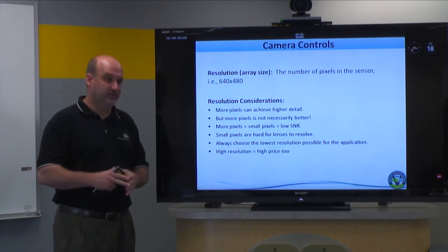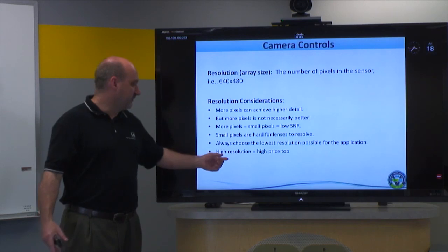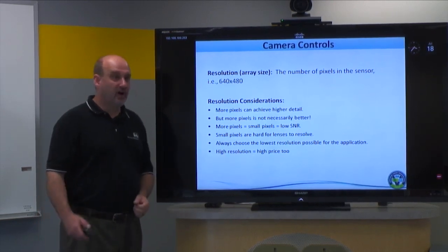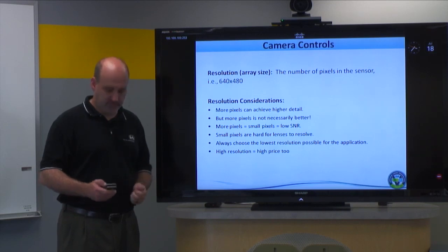If I don't need them, then you should make this a balancing act, because more resolution means more data to transfer and more data to process. Higher resolution also means higher price, because you bought a higher-end camera and a bigger imager from somebody.